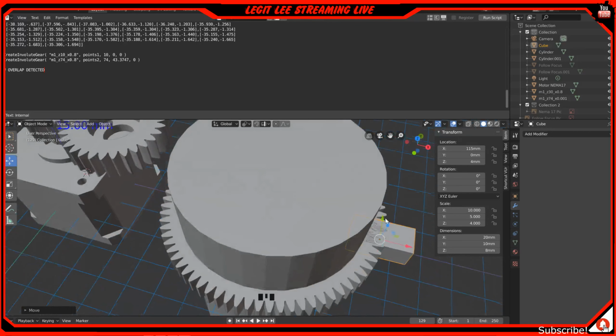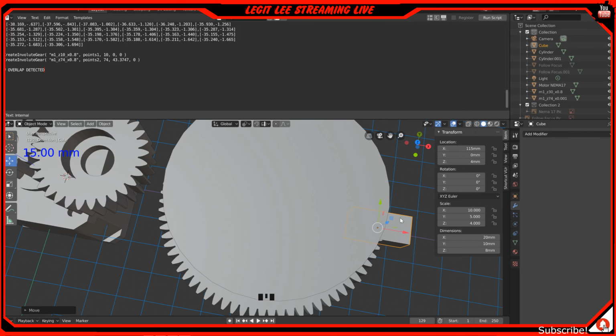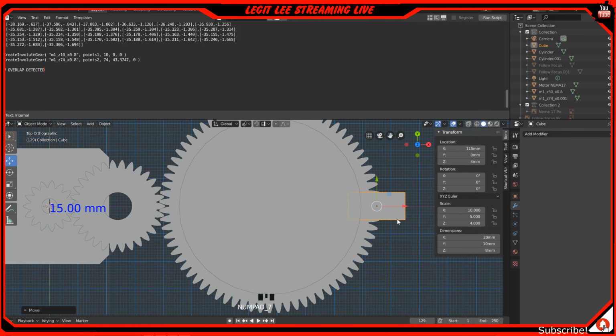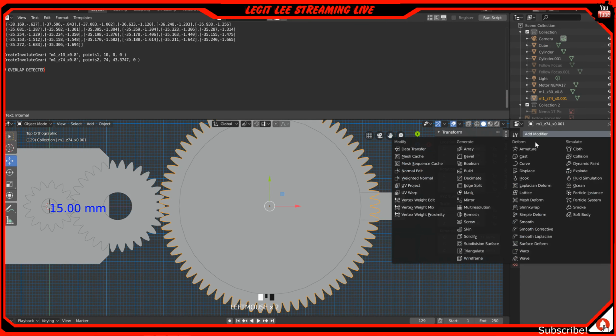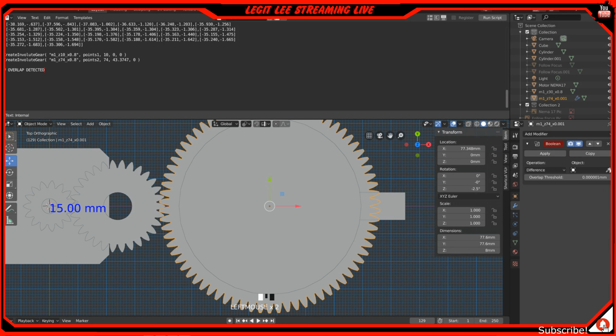I like that design. So now we have that, we'll do a Boolean modifier. So we're going to hit this guy, hit Boolean, add this guy as a join, not a union, not a difference, and we're going to hit apply. And now we can delete this one.